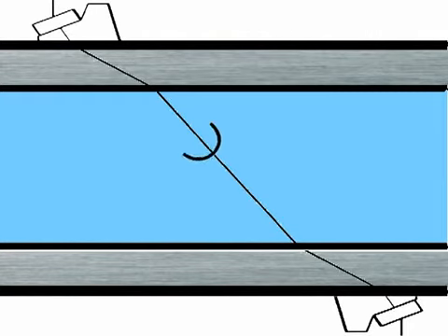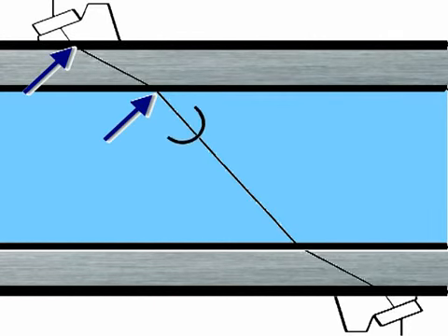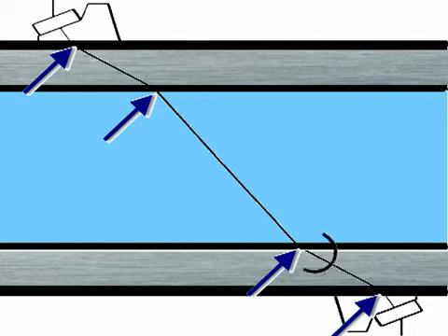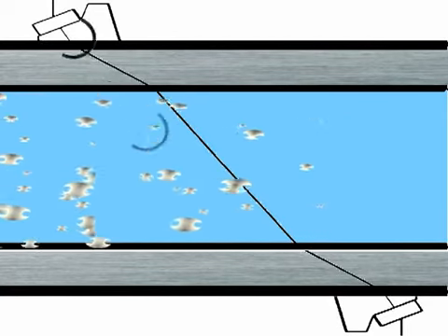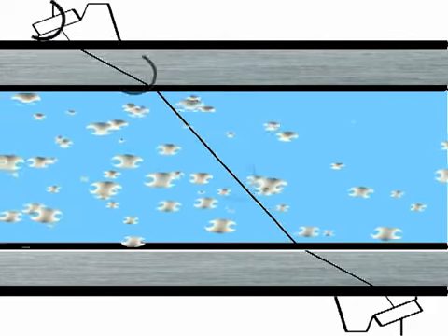For us to get both of these signals across, we have to firstly place the transducers very accurately on either side of the pipe. To do this, the refraction angles of the ultrasonic signal as it passes from one medium to another need to be known. This refraction angle is a function of the speed of sound in each of the materials. We also have to ensure that none of the materials through which this ultrasonic signal passes excessively attenuates or disperses the ultrasonic signal.